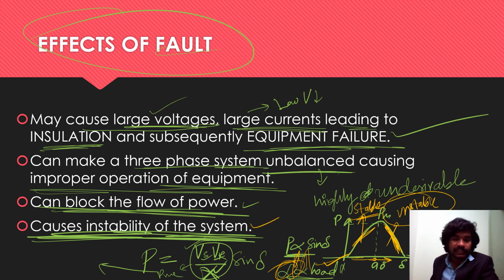So it is very essential that you detect the fault early and disconnect it from the system. You have to identify which section of the power system is subjected to that fault and immediately disconnect it from the power system.